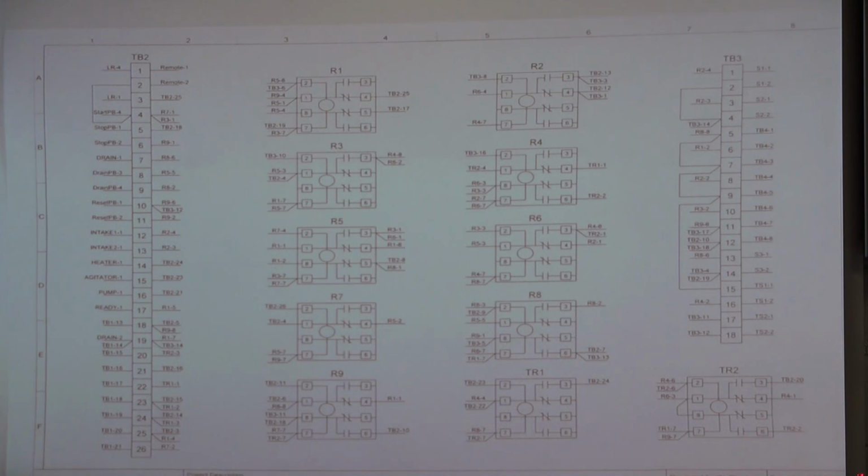And it probably isn't real healthy for that heat to be trapped in that box over and over again. It would probably begin to degrade things around it. So keeping that fan blowing 15, 20, 30 seconds, however long, is a timer relay. In heating and air, it's usually called a sequencer, but it's really a time circuit, that's all it is. And last but not least, page 5.